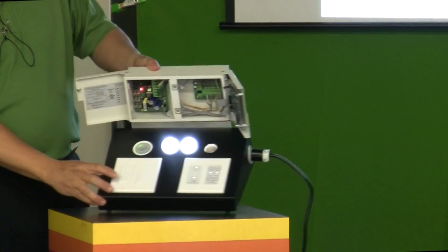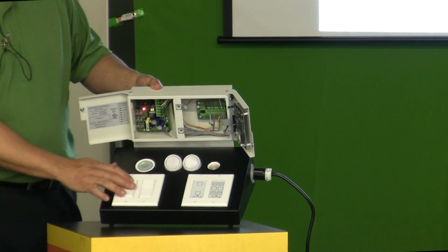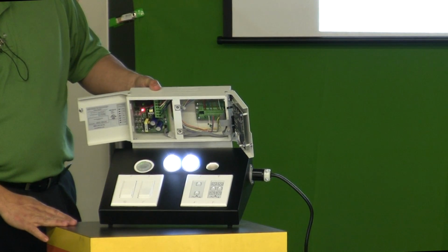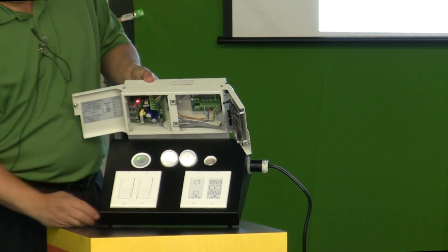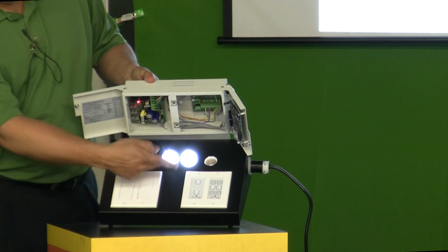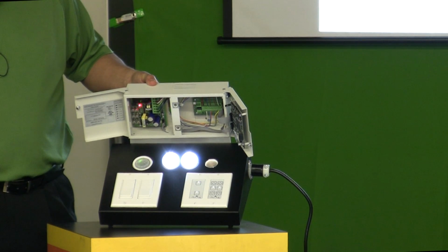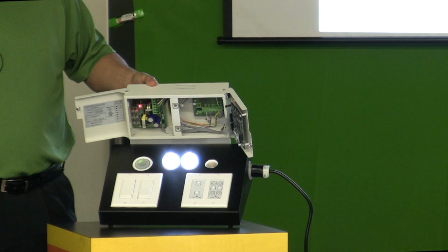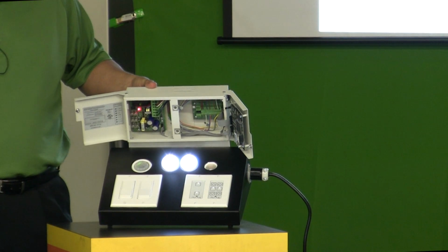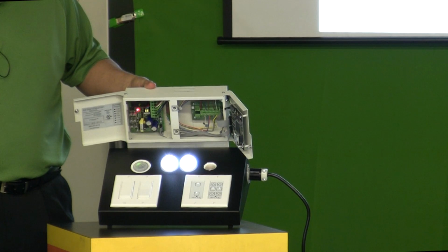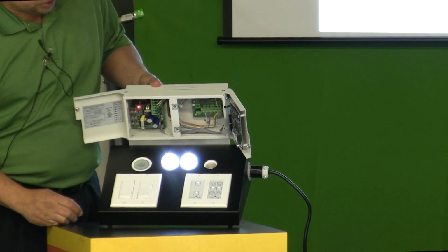So these are 2 Decora style line voltage wall switches. Nothing special. That's turning the lights on and off. I also have an addressable station here, and they have pilot lights on them or indicators. In the energy code, if you have a switch that's a master switch or remote from the space and you're not in the space to see the lights, you also have to have annunciation on the switch. So those are the kinds of things you've got to think about when you're trying to meet the energy code.